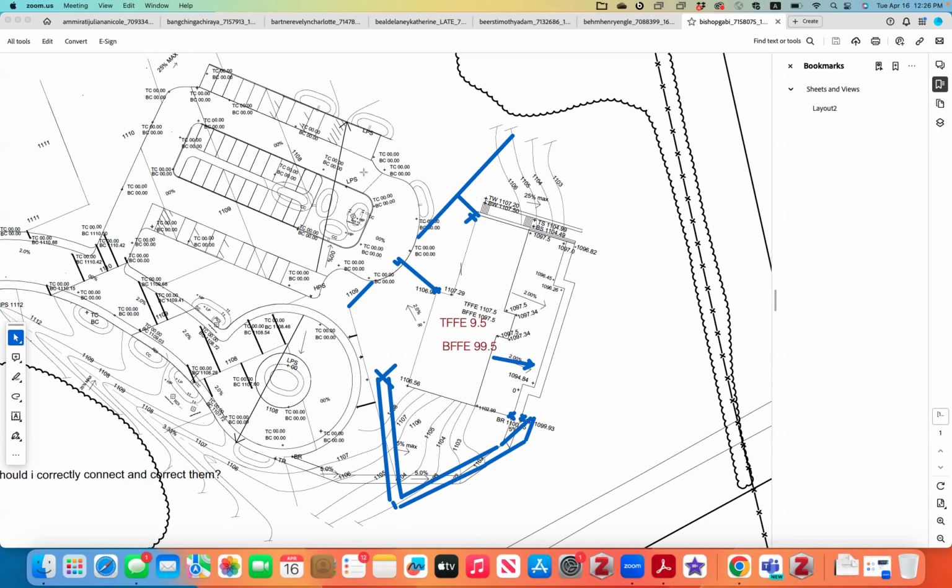The folks that come out of the car on this side wouldn't be able to see the entrance of the ramp over here. That's why it's better to put the ramp over there. Okay? And for the 2% behind the building, those would still be okay. Yeah, those are okay. This slope also needs to be in this direction, perpendicular to the contour. Yeah, that 2%. All right, so that's about the ramp.